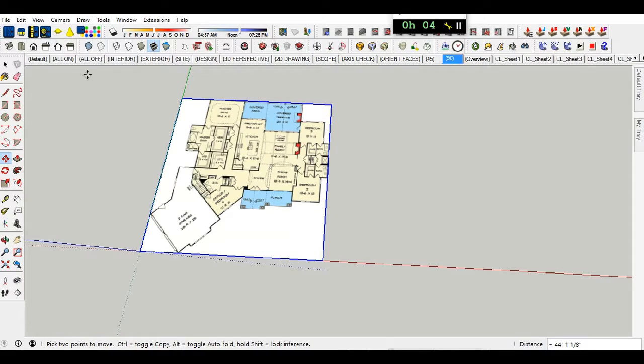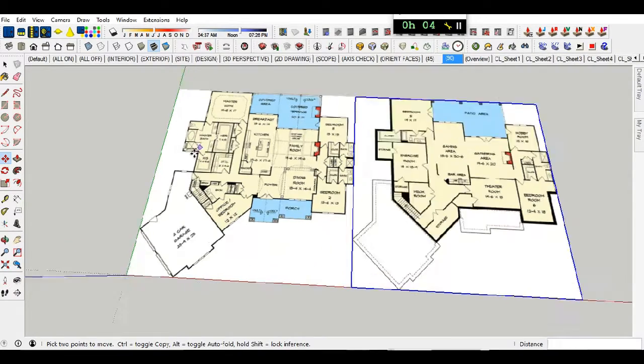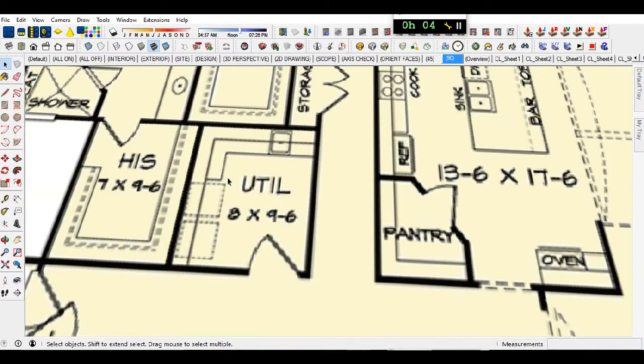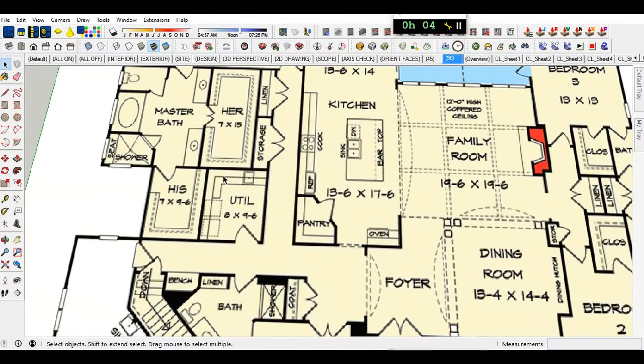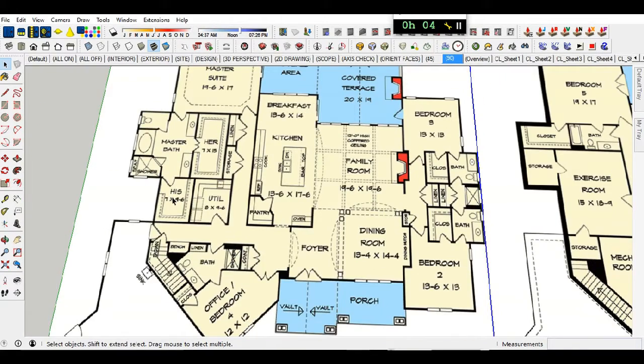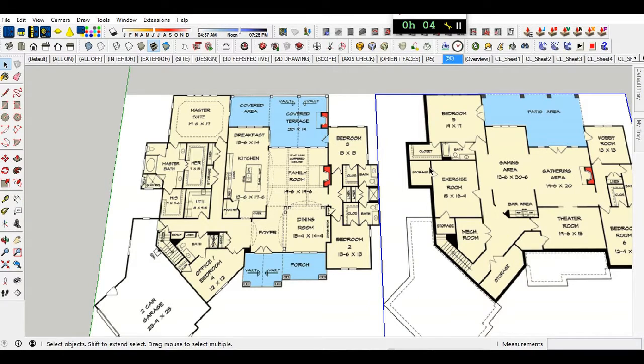That will resize everything in the model, so that now if I take a measurement with the tape measure tool on this down to here, we get 9'6". So now all of these rooms, once we draw them in and push pull and so on, should end up being their actual size in real life, which will come in handy when we are trying to figure out where stuff should go if we were to be moving into this house or whatever.